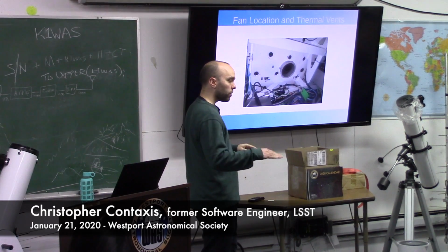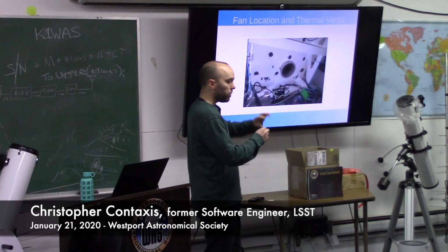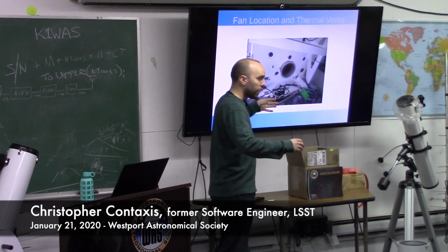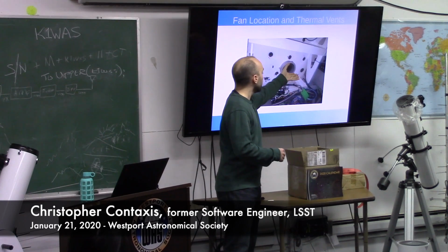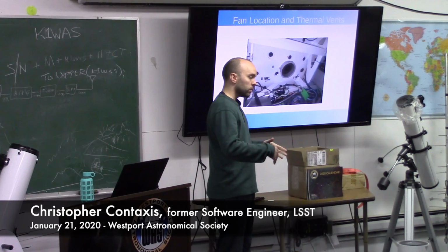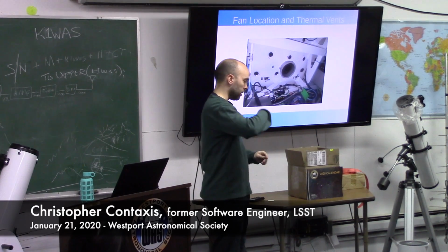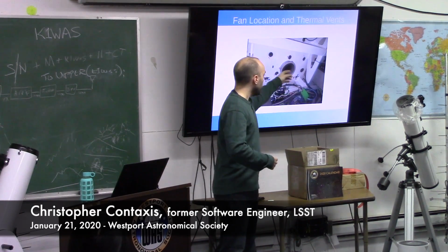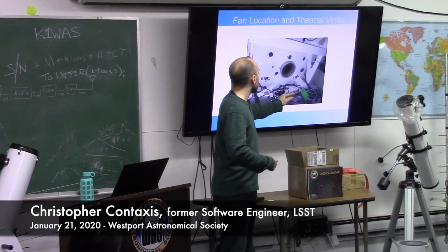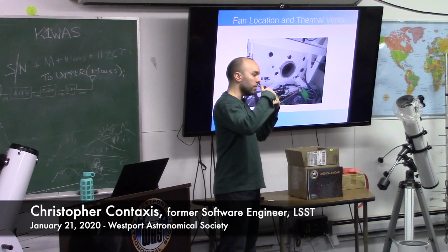And the idea here for the thermal side of things is you can move that tube up and down in the core and position it so that the cooler air that would be here in the cell gets circulated up into here, because the fans here are pulling air from the other side, underneath the mirror, into the cell. So that puts a slightly higher pressure in the cell than there is under the mirror. So that creates a circulation where this higher pressure air that's been conditioned by this fan unit wants to, just through the pressure change, go up through these pipes into the backside of the mirror.